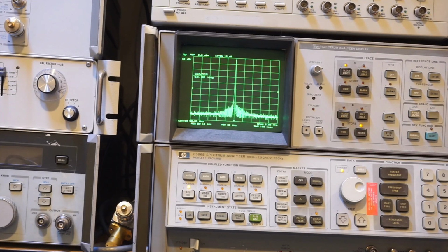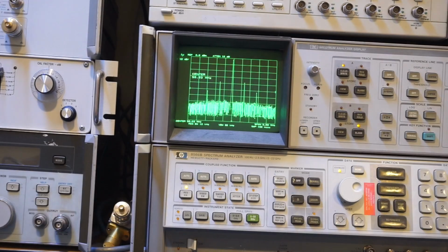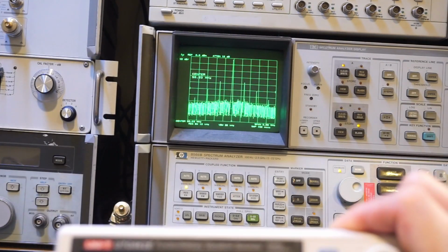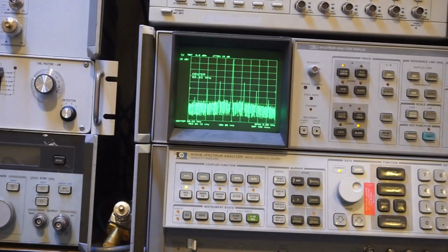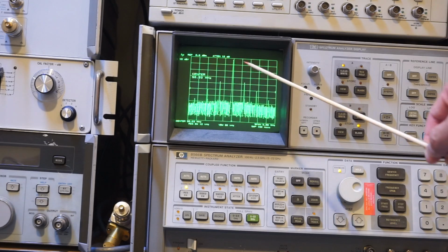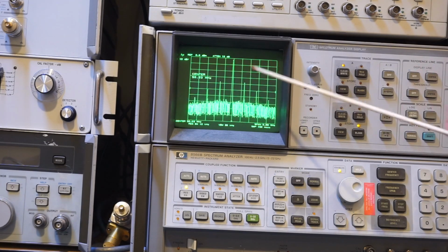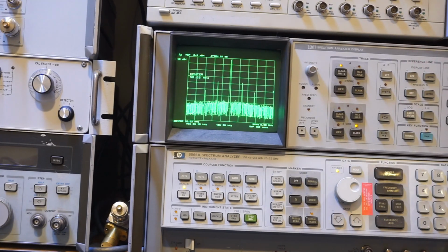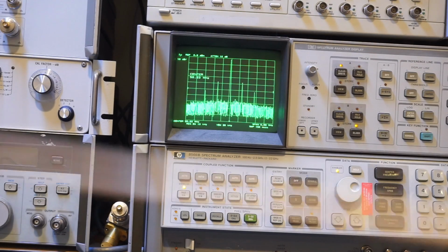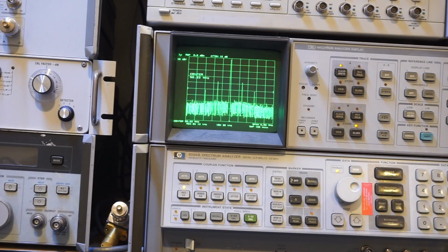Now let's do a quick comparison with what the signal output looks like at the same frequency on the UTG4082A. And here is the same 50 megahertz, except this time it's generated by my UTG4082A, as you can see here. And you can definitely see there are a lot of harmonics going on here, and these are actually only about 30-40 dBs down. Now that is actually still pretty good, but from a spectral purity perspective, there's no comparison between the 962E and the 4082A.